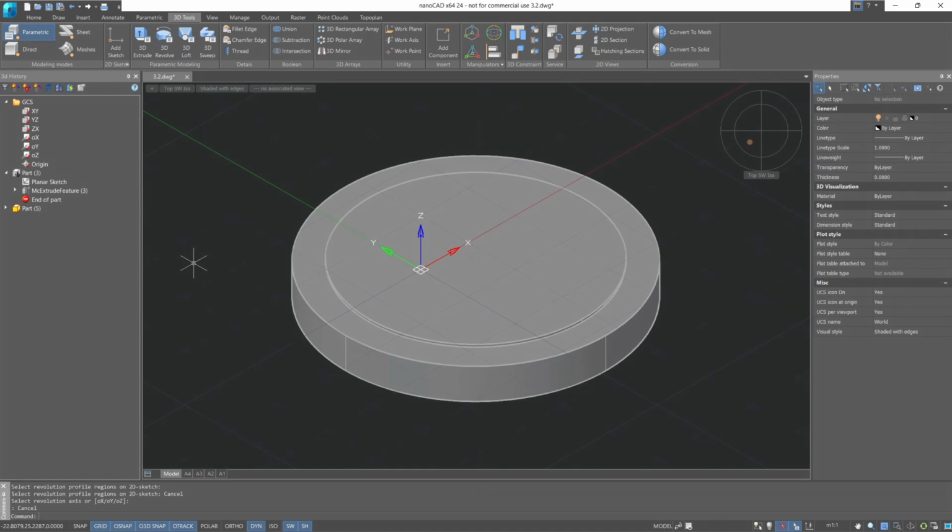I also think it's important to mention that using Boolean operations for union, subtraction, or creating intersections between bodies of direct and parametric modeling should be avoided to prevent unstable software performance and errors in 3D object geometry. This concludes the part of the parametric modeling lesson dedicated to extrusion and rotation operations. When you are ready, proceed to the next part of the lesson.